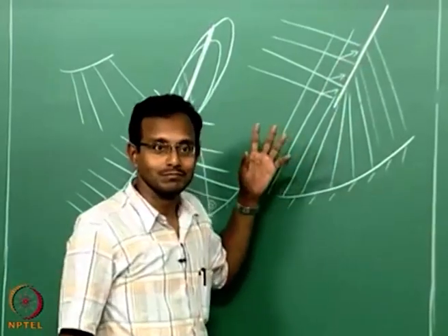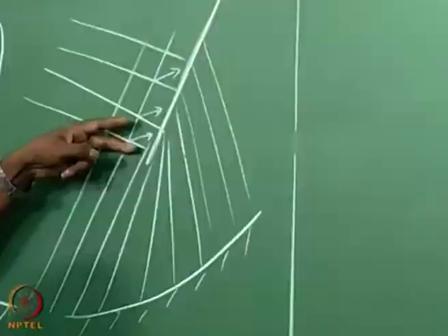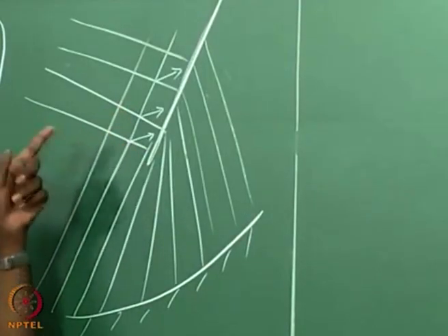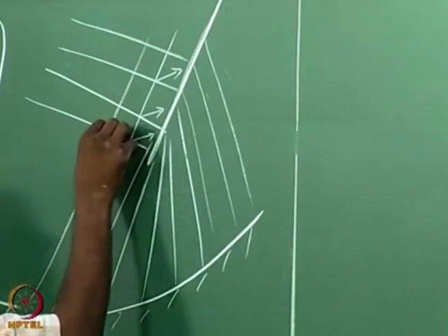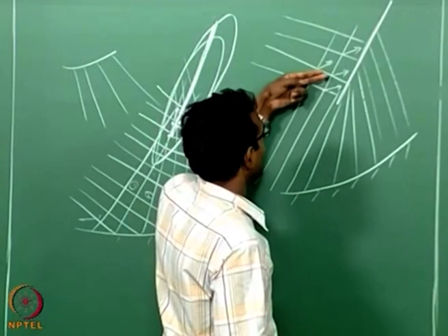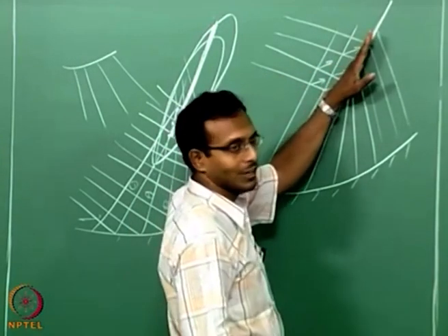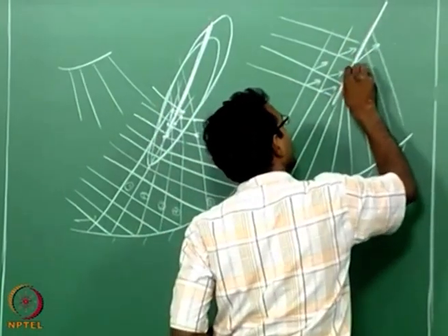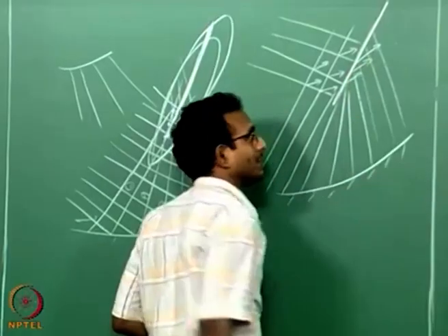Hopefully you remember this. Okay. Characteristic lines are your two Mach angles, which means the angle bisector between them will be your velocity vector direction. Velocity vector direction for each of these cases is something like this. Angle bisector. Now when there is flow coming like this and there is an oblique shock like this, flow will turn more up. So it will be like this finally. Final velocity vectors are like this.